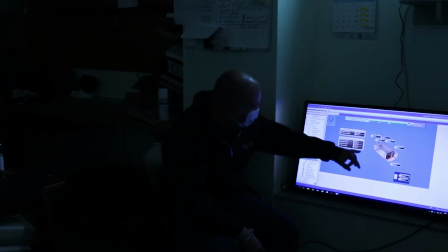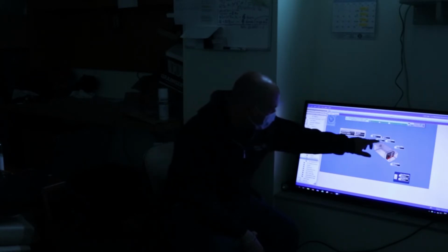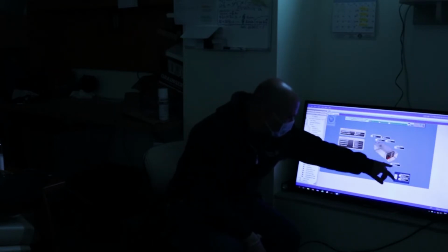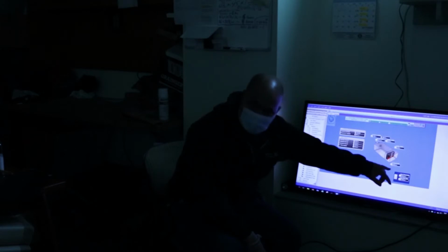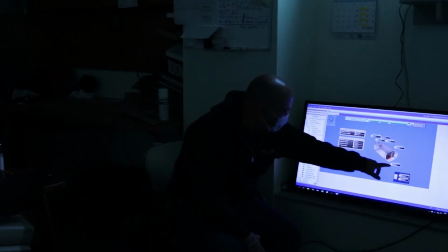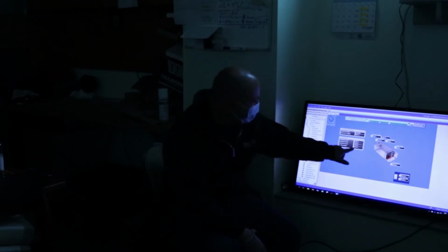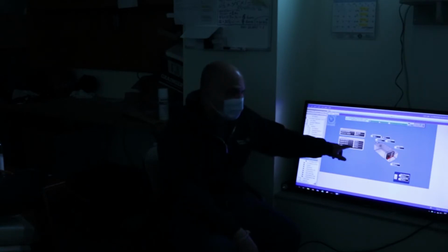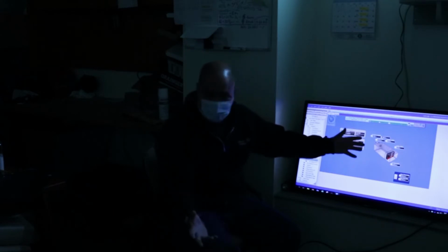Basically, really the discharge air set point tells you the AHU, what's coming out of the air handler, right? And then you get a local reading of what's coming out of the VAV box. So you can see the heating valve is at 15%, so it dropped. Everything seems to be working. We do have a max on the heating set point. It doesn't let the coil go above 92 degrees. So that's everywhere.